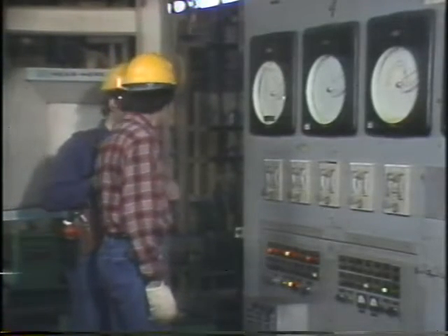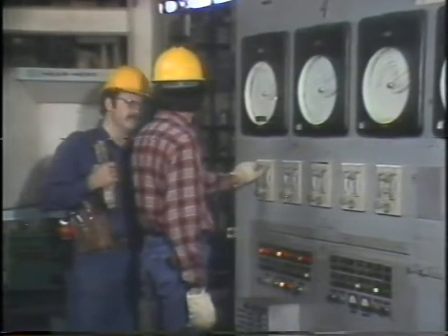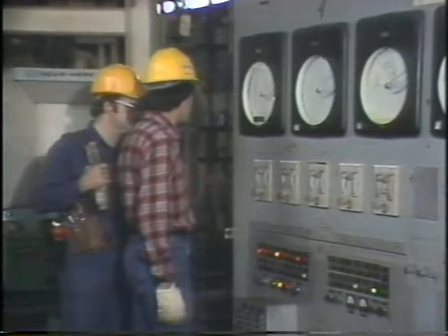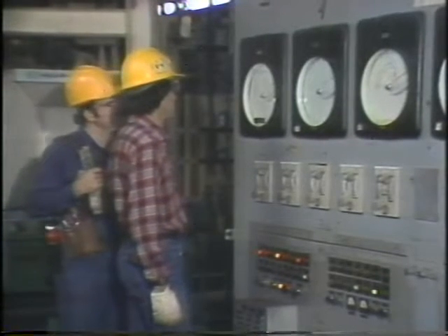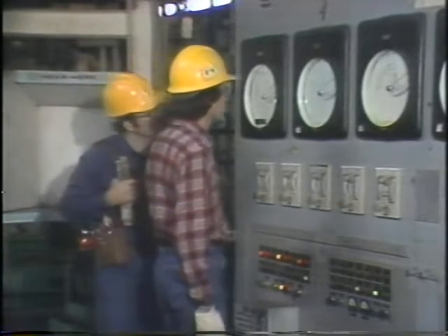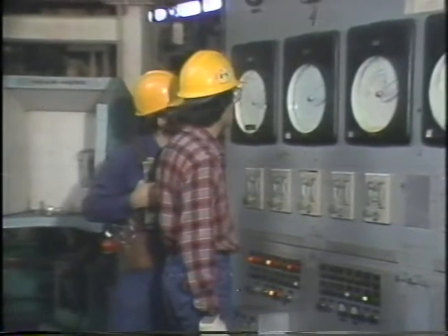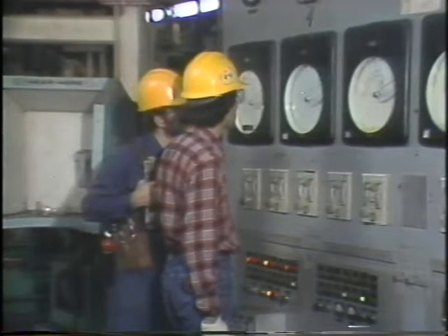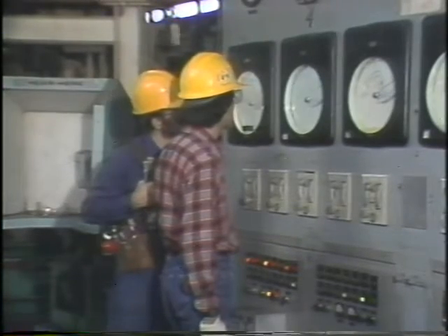When Bob talked to the operator to tell him he'd corrected the problem in the feedwater transmitter, he asked the operator to put the system back in automatic to see how the system worked. Then the operator put the system in automatic, and they made a visual check of the system's indications, looking for any problems. With the system restored now, the feedwater flow signal should have increased, causing the control system to bring the drum level back to where it's supposed to be.